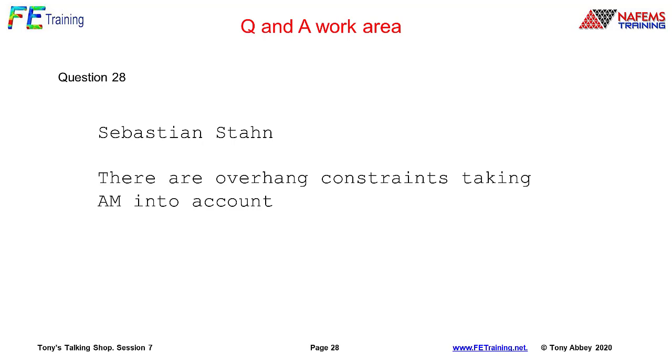At that point, your additive manufacturing process collapses because it can't support itself, or you need to put supporting material underneath there. So there are overhang constraints to say we mustn't have an angle shallower than a certain angle, which gives us a more robust static solution to our structure as we build the arch type structure. The direction cut we take to create that additive manufacture also dictates that.